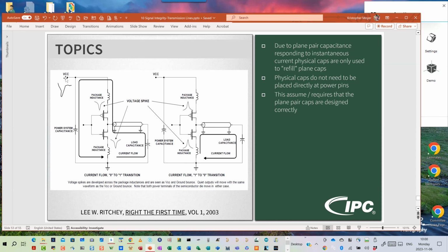So based off of your design, if your capacitor's rated for, say, 25 volts, and you're consistently going to 25 volts, now you're stressing it. If you're 25 volt rated and you're switching 5 volts, you're never approaching its maximum rated working voltage, so you're fine. The stress that the capacitor sees is going to be thermal, moisture, environmental, shock, vibe, and voltage. This fast switching, you're going to be fine.